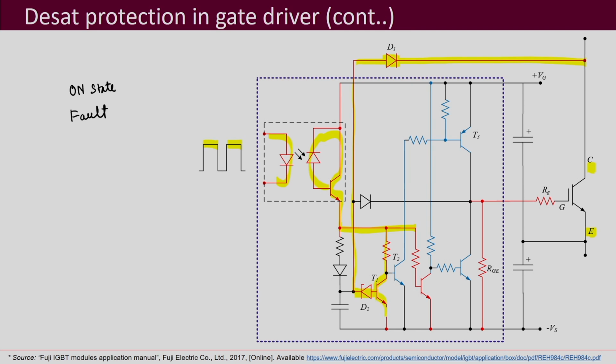and so this T1 turns on. So, this T1 turns on and it's pulled down. If this is pulled down, what will happen, this T2 will become off. T2 goes off, that means T3 will also go off because it gets connected to the high potential now, and this is PNP. And then further else is the same. So, this is high, so this is also shorted, this is pulled down, so this is also off. So, now we have to turn it off. So, we saw that this T3 is now blocking, it is not conducting. So, if it is not conducting, this is also off.